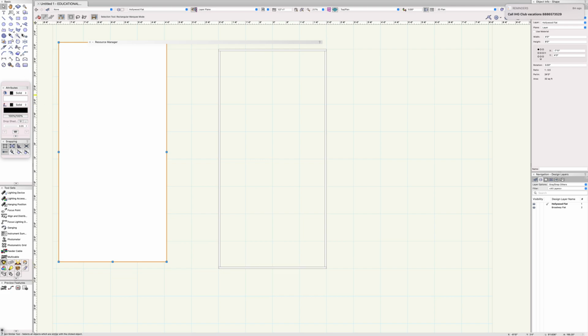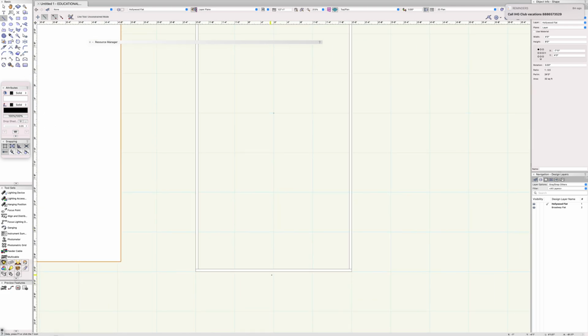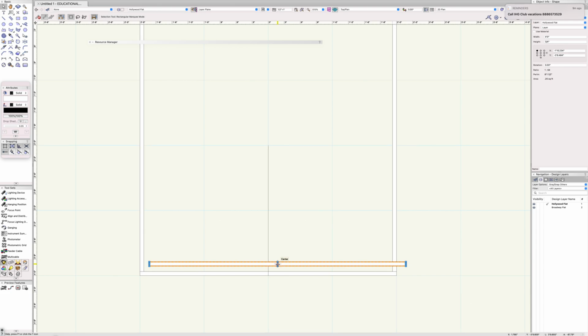So the simplest way is that I will draw a line from the bottom of the bottom toggle, a 2 feet distance line. Now this is my reference line, and what I can do is either duplicate this one, copy and paste this one, or, because this has already a size given, I will duplicate it, which is Command D or Control D. I'll pick the center of this toggle and put it in the center of my 2 feet reference line.